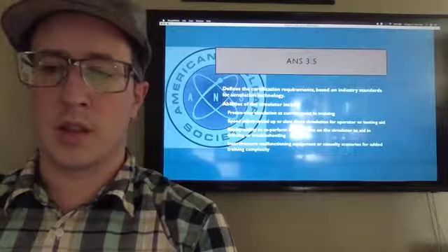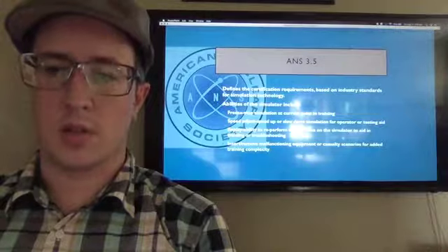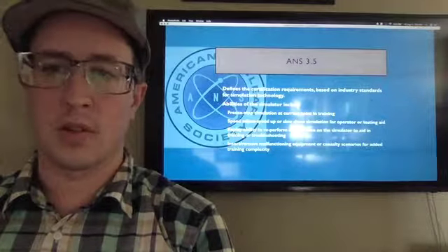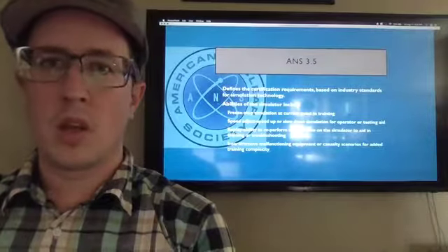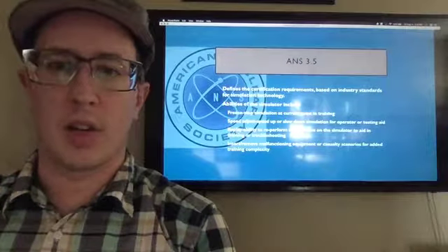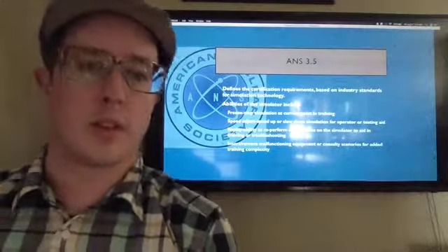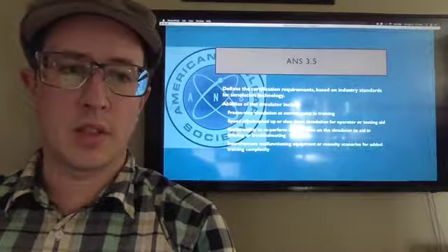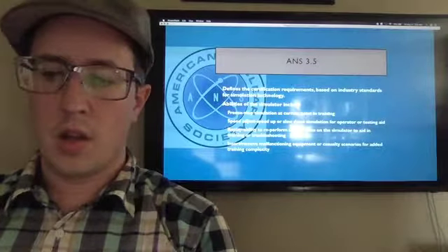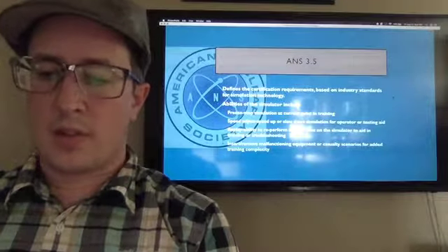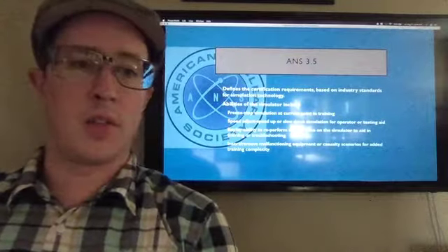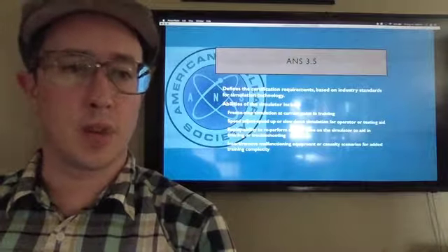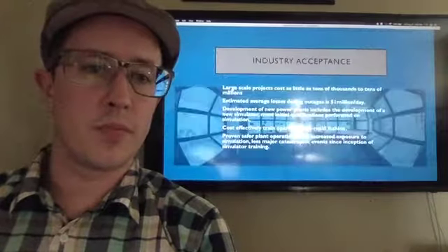It allows the instructor to insert some sort of abnormal situation, for example a turbine bad bearing, a loss of coolant accident, or even loss of vacuum, allowing the staff to insert an anomaly on the student and forcing them to react and figure out their correct operations.